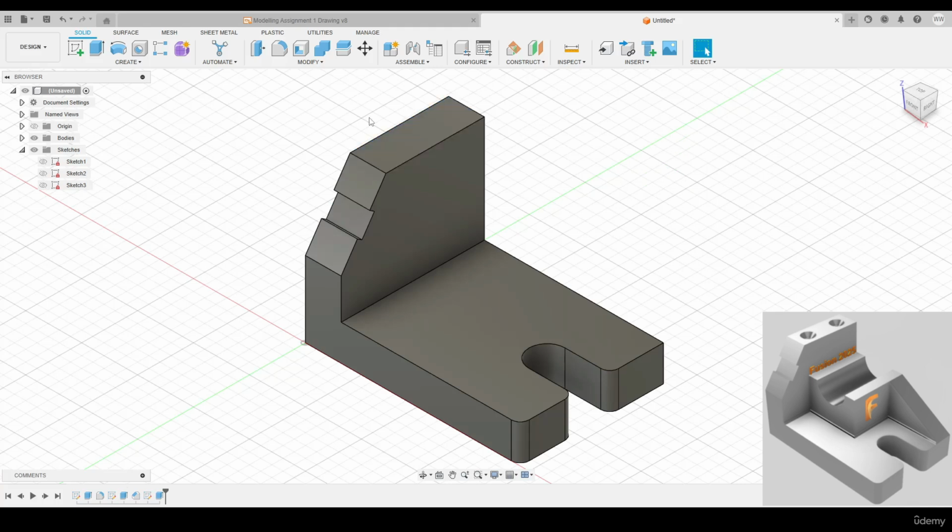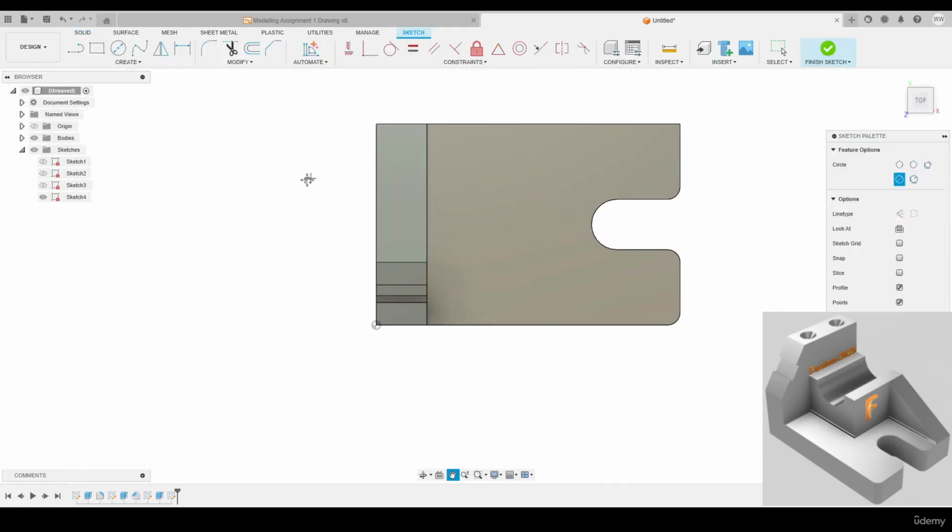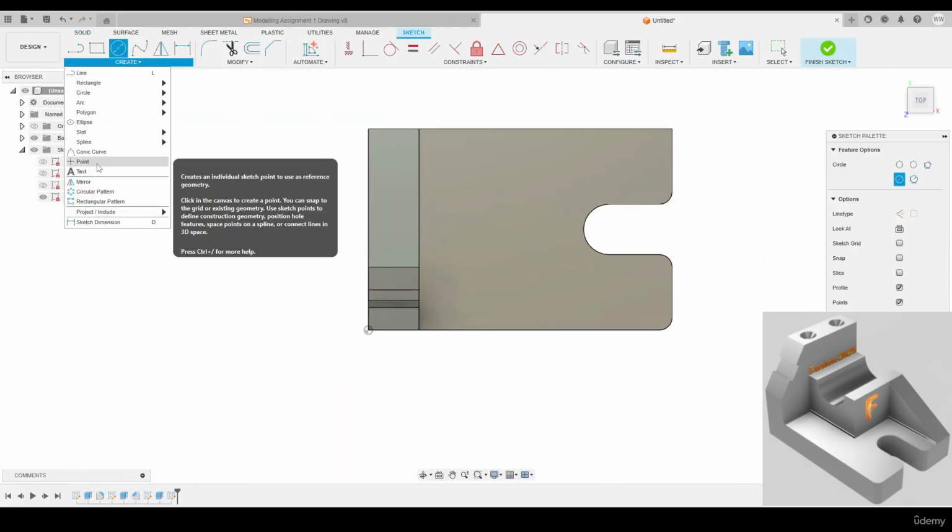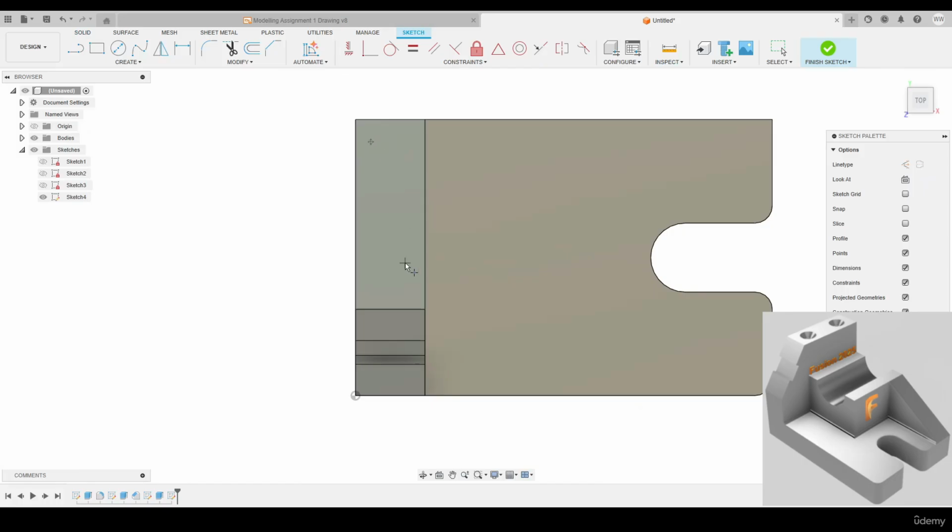There are two holes, so within the hole tool, we need to use points to identify the location of those two holes. So we need to do a sketch for that. Hit C on the keyboard, select this face here, come under the creation tools, select points. I'm going to throw in 2 points anywhere for now and dimension these up. Dimension the first one. From the top horizontal, we've got 10 mil. And then let's align that with a vertical constraint. So from this point, hold down Shift on the keyboard, select the midpoint of this line. It's now fully constrained.